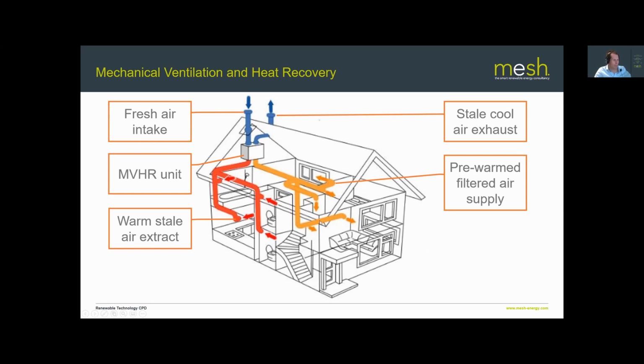What you find is that the bits that typically architects tend to miss out on is they forget to leave enough space for this ductwork, and it can make the ductwork installation quite tricky to design. So please, architects, leave plenty of space for ductwork, and remember that ducts don't go through things very well. So when your structure is being designed, think about leaving a void where you can run those ducts uninterrupted.